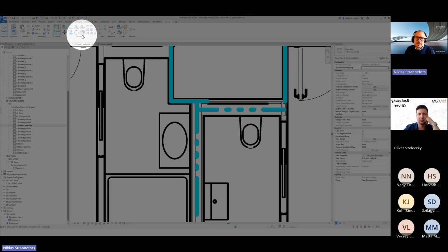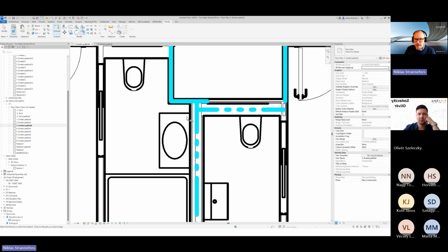In AutoCAD, we click on the line that we want to remove. So we would go here. In AutoCAD, we would click on this side and remove this corner. In Revit, it's reverse. So we want to keep this one and this one, and that can trim everything. And we want to keep this one and this one. And we can start trimming and fixing so it looks good.